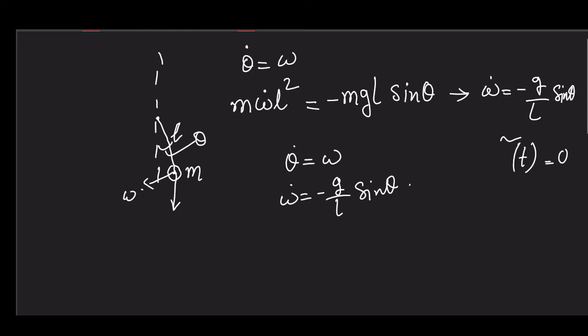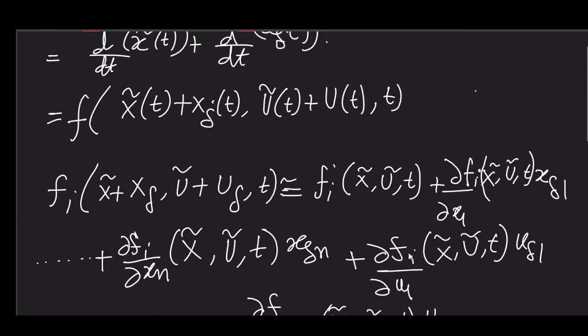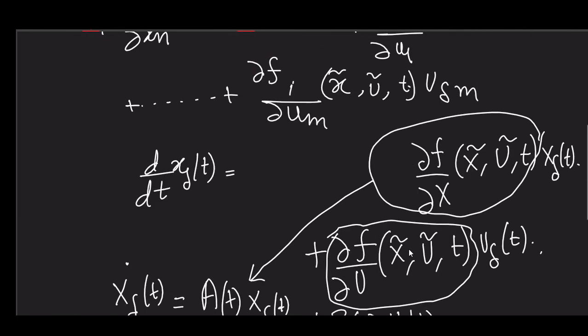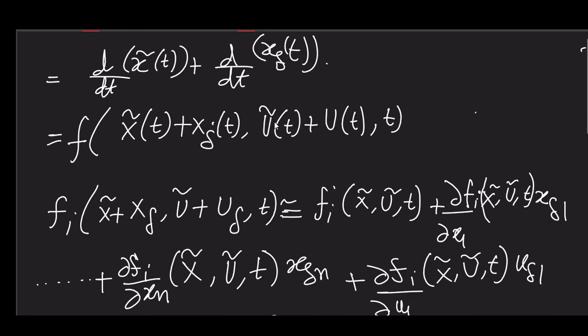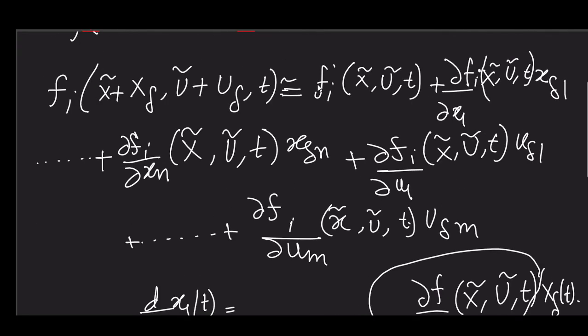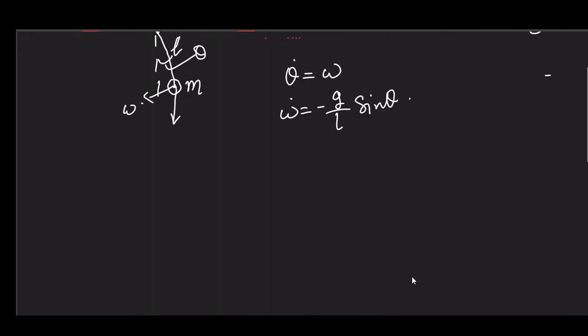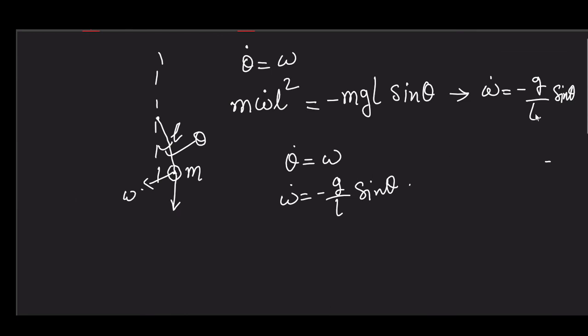In the above equation, we can safely drop the second term because u delta t is 0. We are considering a force-free system, so u nominal t and u delta t are all 0. What remains is the linearized model of the system around its equilibrium point.